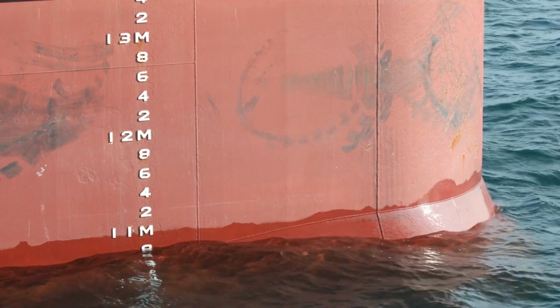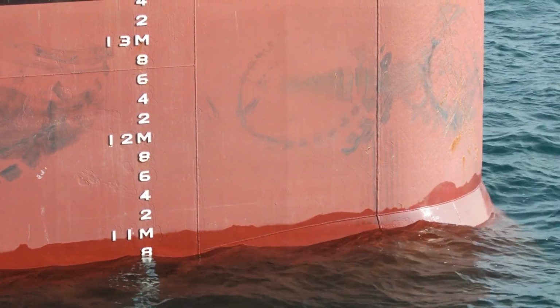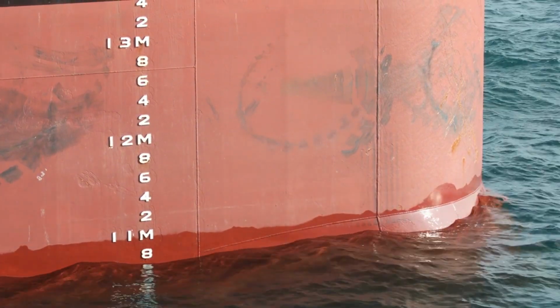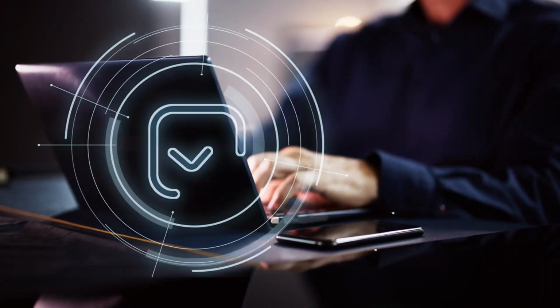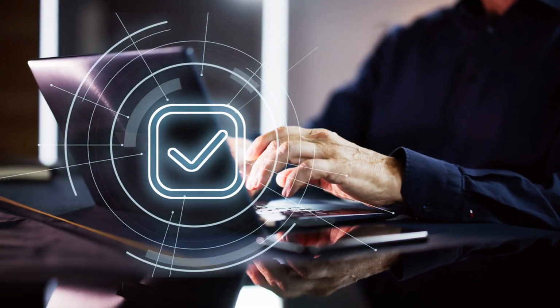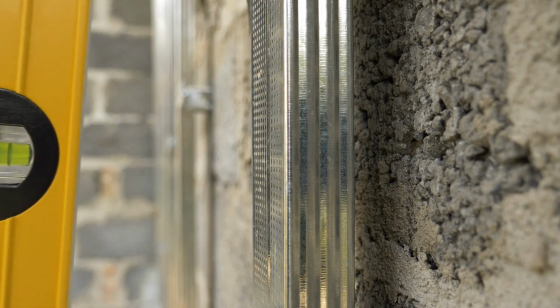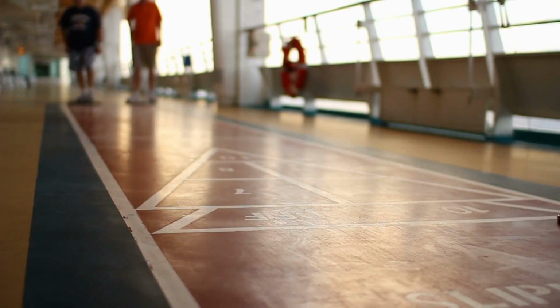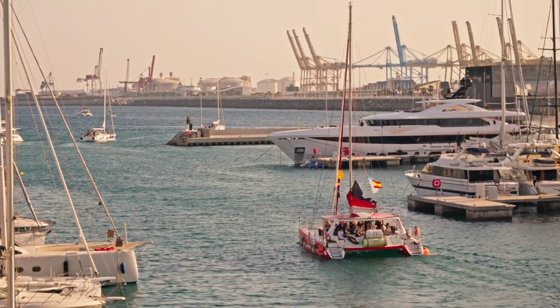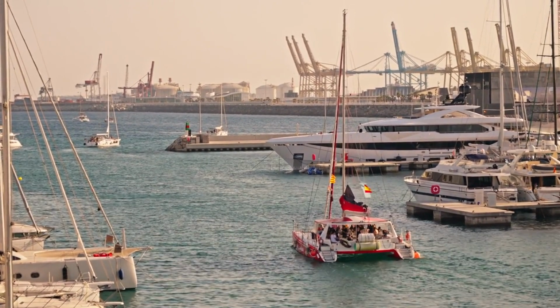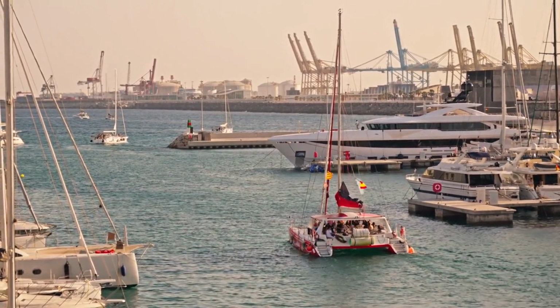1. Ensure the vessel is in normal seagoing condition, upright, and with no magnetic objects near the compass. 2. Check that the lubber line is in line with the boat's fore and aft line. 3. Select a distant landmark clearly visible but far enough away to prevent parallax errors. 4. Slowly swing the boat in the smallest circle possible. 5. Take a bearing on the landmark on at least 8 equidistant spaced headings, keeping the boat steady on each heading.